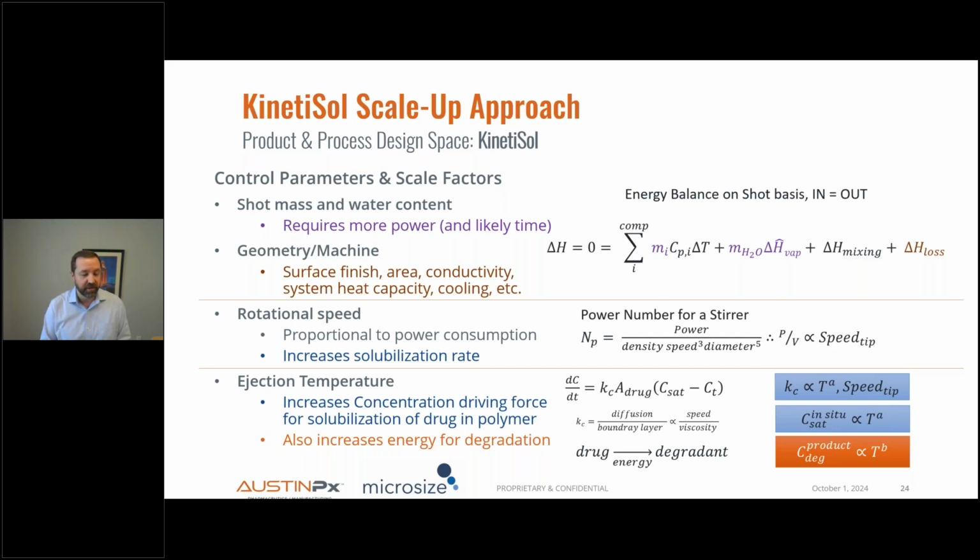RPMs are sufficient to achieve drug dissolution, which is also significantly impacted by the temperature at which we process the material. We know that quite a few melt extrusion and certainly most KinetiSol processes utilize a dissolution process where the process heats up the carrier polymer, it softens and becomes a solvent for the drug, which dissolves into that.